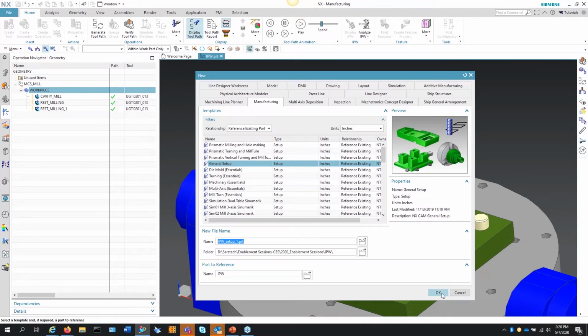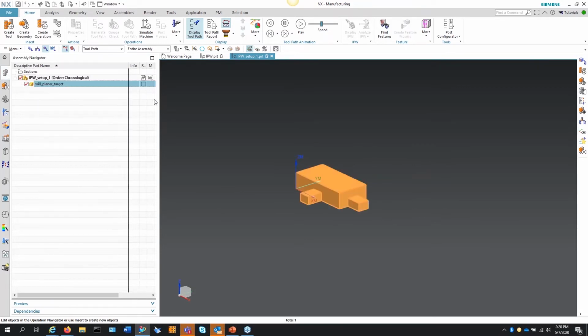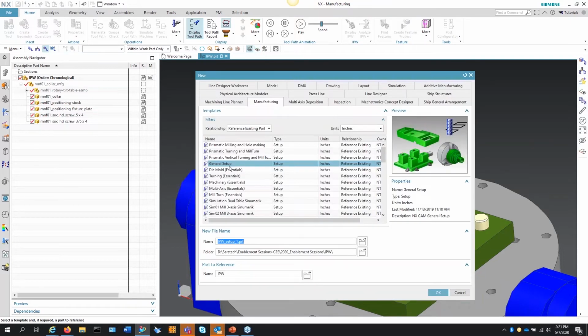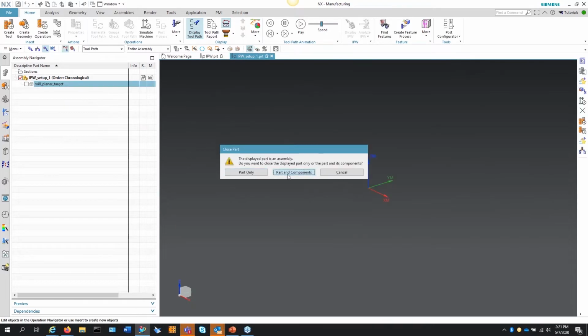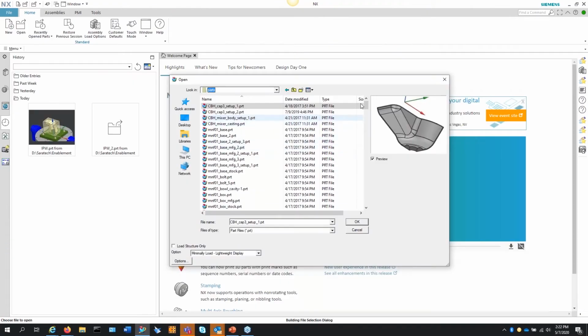Everything looks good here. And what this does for you, if you go directly, I chose the wrong one, sorry. What it does is it takes your singular component file and puts it into an assembly. And if you do not do that, you lose WAVE geometry linking ability. You have to manually set up your assembly file. This does all this for you. So anyway, what I'm going to do is open up another part and show you that.